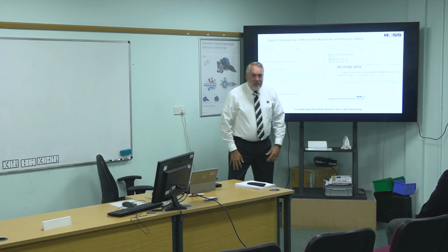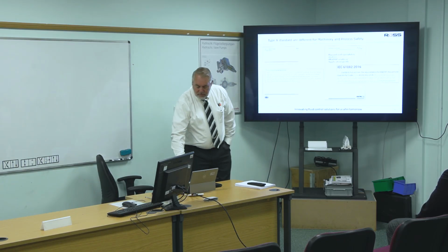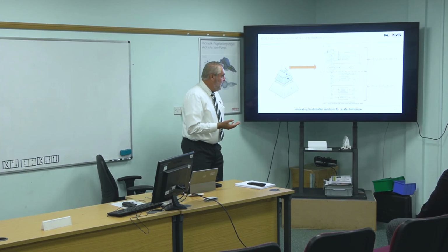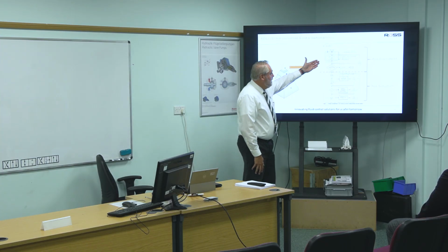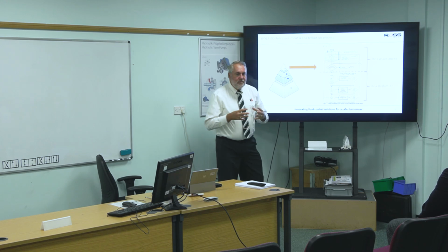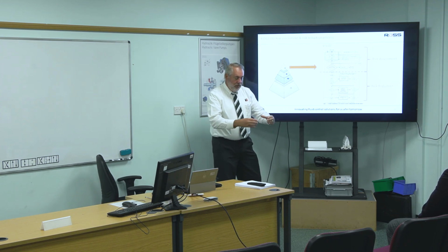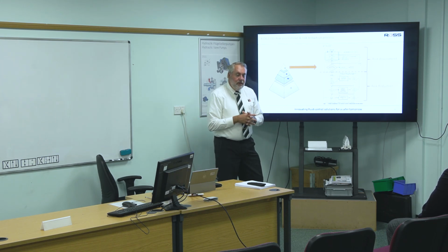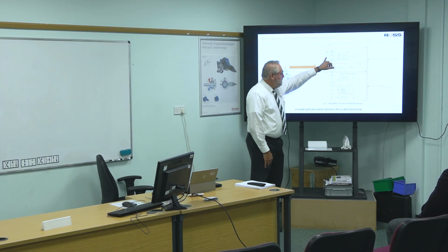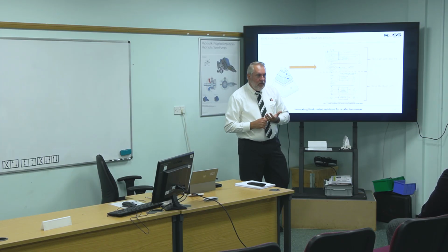So it kind of falls on both sides, depending on what type of manufacturing you're doing. The ISO 12100 standard basically defines the requirements for risk assessment and risk reduction. And it says right here, you need to determine the limits of the machine. Is this machine one station or is it a line? And then what are the operating speeds? What are the voltages, the pressures, things like that that the line's running at? That's determining the limits. Then you have to identify hazards associated with running that line.